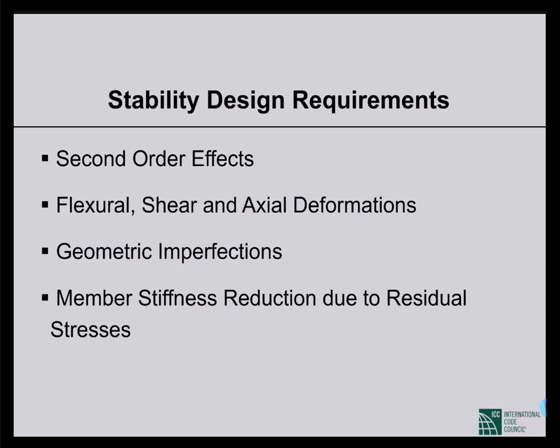But here, the way the residual stresses are introduced in the member is different. I'll talk about that. Once there are residual stresses, already some compressive stresses in the structure, it reduces the capacity to allow for more compressive stresses. It will buckle earlier. So these are the 4 things that are very important from the stability point of view. In any design, we have to consider these 4 effects.